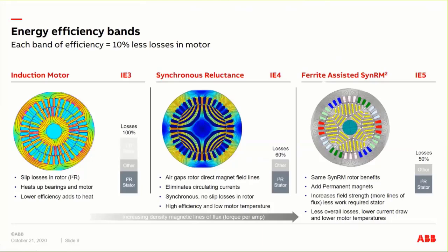So in a lot of cases, you look at a 15 kW or a 20 horsepower motor, it's typically in a 280 frame, or I believe that would be an IEC 132 frame, or maybe higher. But we can go down in size. We can put a 20 horsepower, 15 kW in a 210 frame. So it's a more power dense design because it has basically less losses in it, generates less heat, draws less current.